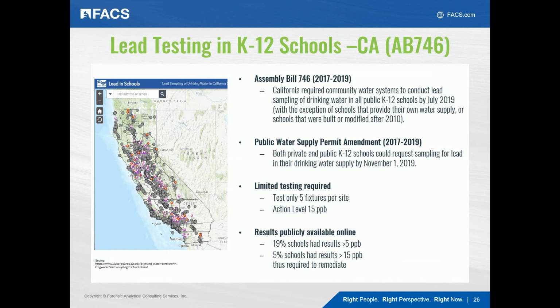But as far as differences in sample size, a smaller sample size is going to tell you more about localized contamination. So the 250 ml sample is going to tell you more if there's contamination from the fixture. A 1 liter sample, that's pretty big. So you're going to be pulling water not only from the fixture, but potentially the upstream plumbing. So it might dilute the sample if you did have contamination from the fixture, and the result would be obscuring the problem with the fixture. If they were using a 1 liter sample, I'm not sure, but that's an interesting question.